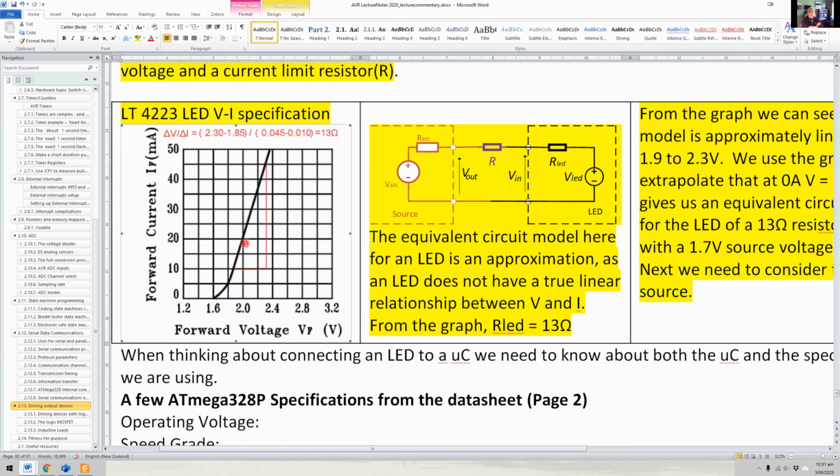Now, this doesn't always happen with LEDs. Some of them have curves. So what you do is pick the range in which you're interested, and there might be a bit of a curve here, but you just pick the bit of the range you're interested in and work it as if it were a straight line. That's the easiest thing to do. Don't get too complex with this, because these LEDs are mass manufactured, and their properties range over a bit of a spectrum. So this will be a typical characteristic, and that's what you'll find in data sheets.